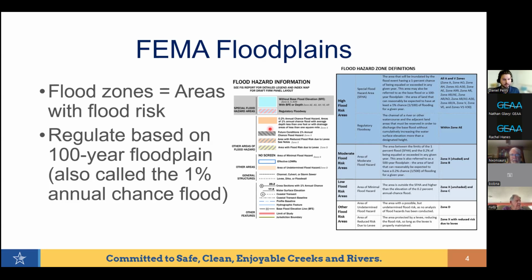And we're seeing the flood statistics change as we get more and better data. So these flood zones specifically guide how and where buildings can be constructed to help protect people and property from flood damage. And again, the 100-year is the main flood that we see FEMA and communities regulate to. And so in San Antonio specifically, we're going to see a couple different types of zones. I'm just going to focus on the major ones that you'll see if you end up going to see a FIRM or a floodplain from the NFHL layer.